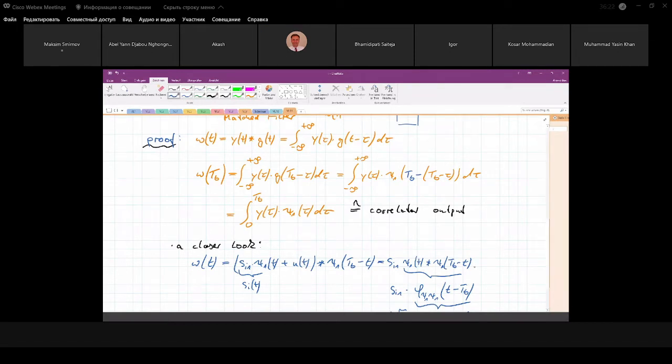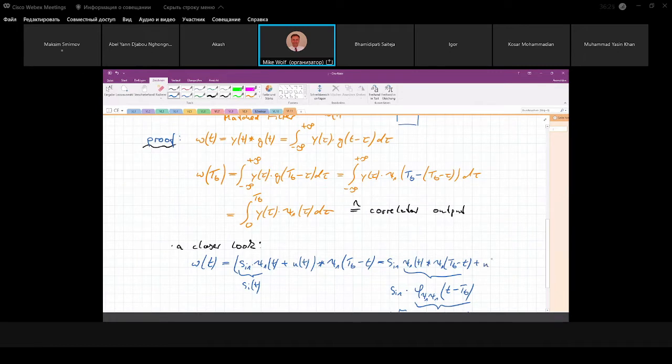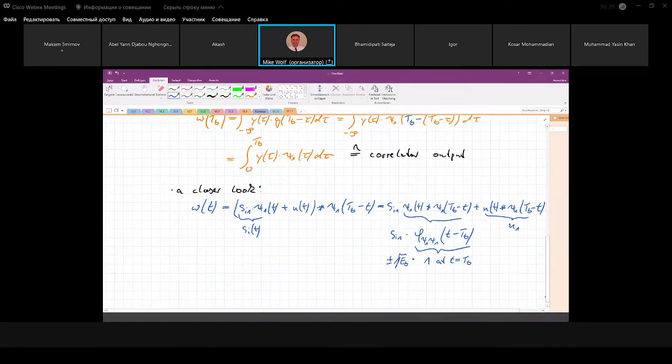So this is basically n(t) plus n(t). Then we convolve with the impulse response of the filter, with c1(t). So this is what we denote as N1. Now we see we have the signal vector component, which is either plus or minus square root of E. And it looks like this function looks like the autocorrelation function. The sampling time gives just our vector component as before.